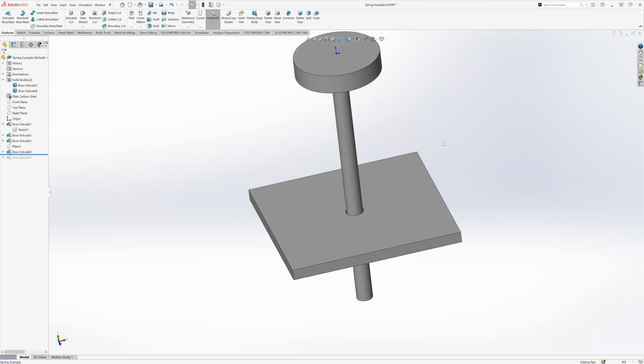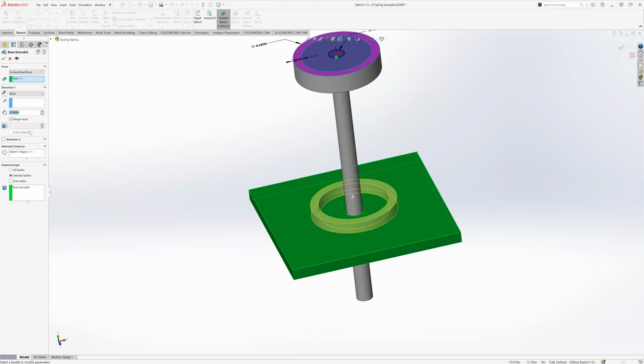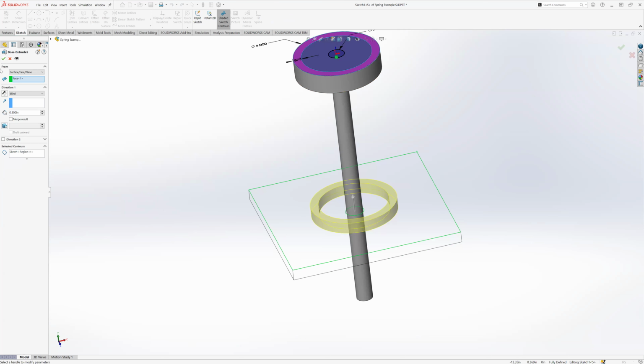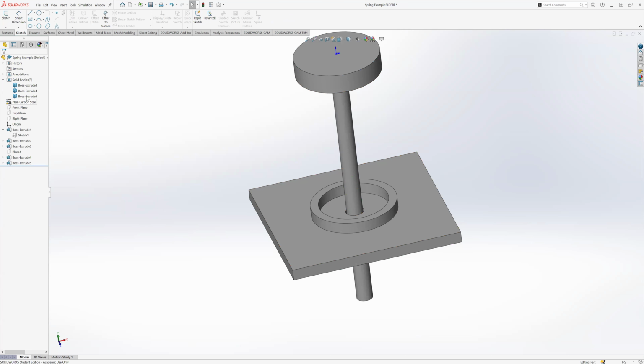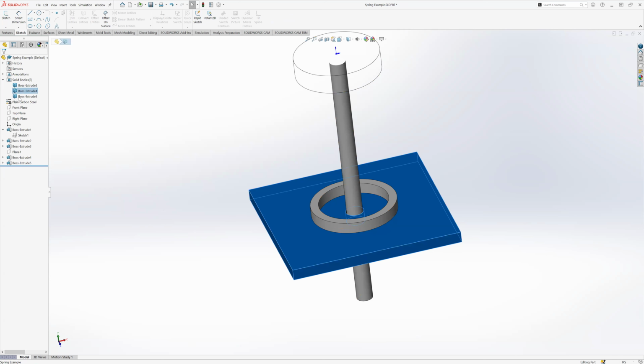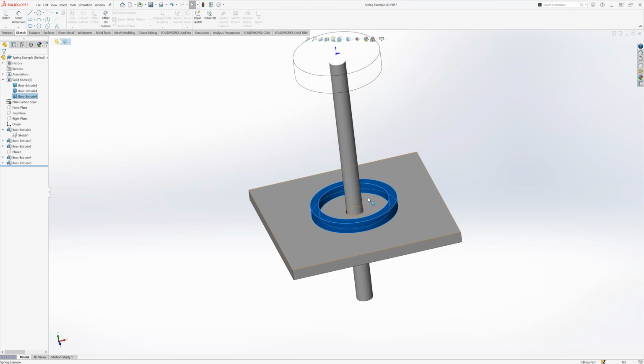So to have one body in SolidWorks, if you're having separate features, they have to be actually touching to be able to merge them into one body. And also when I roll forward here, this is obviously getting merged to this body. Again, I think I might have talked about this in a previous session, but there's a checkbox here that's called Merge result. If I uncheck Merge result in this case, again, this would work for up here as well, now I'll have three bodies. I'll have this body still, then I'll have the base, and then I'll have this ring as well, all as three separate bodies.